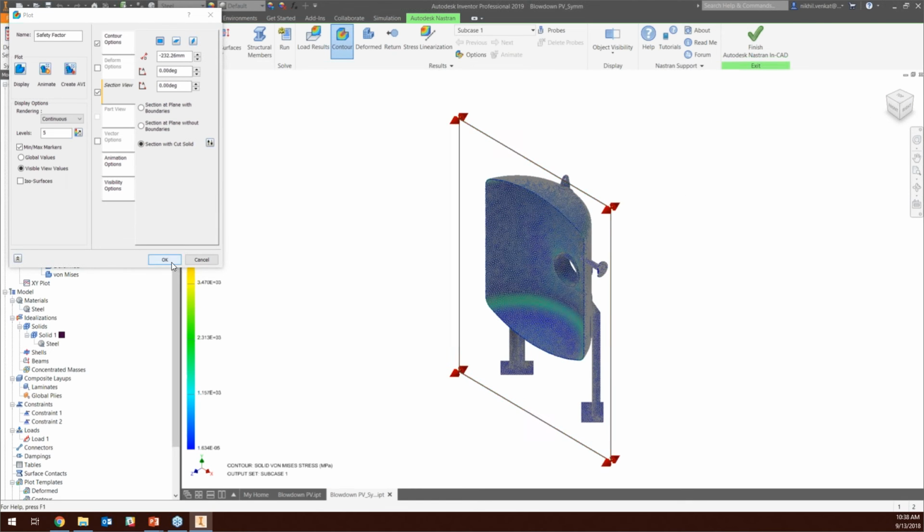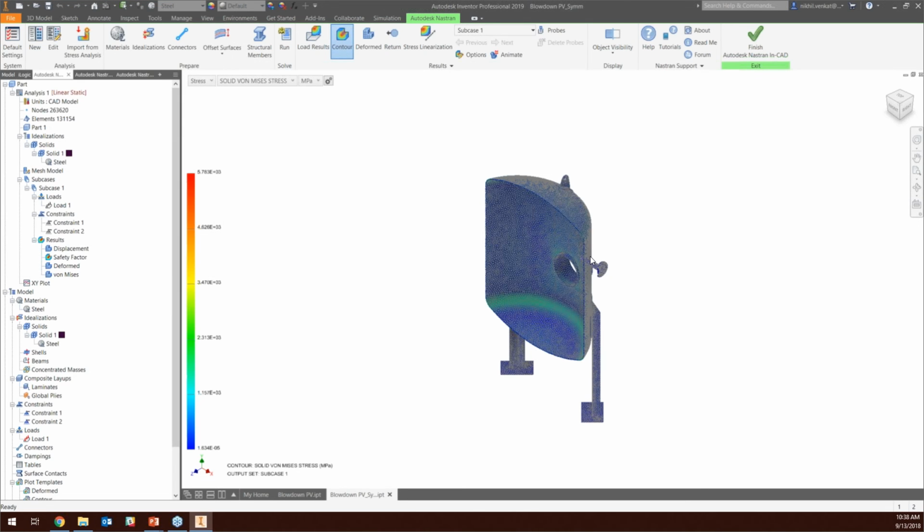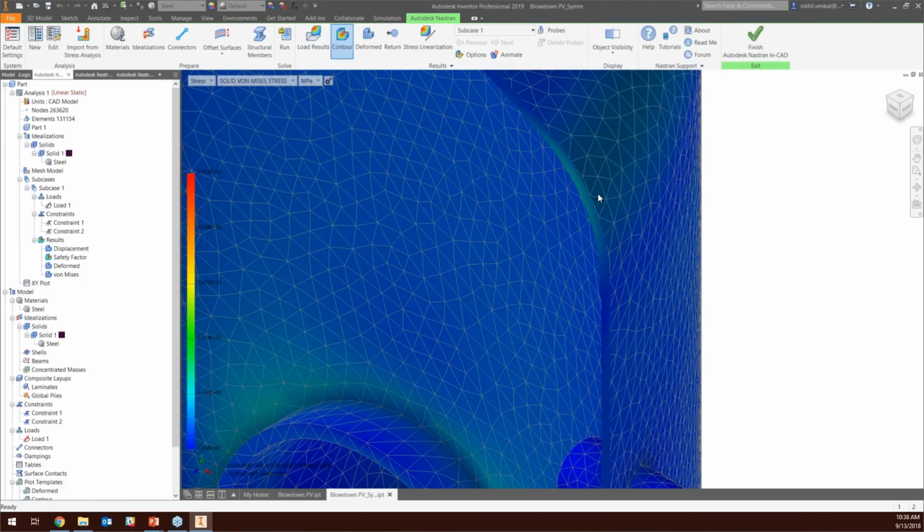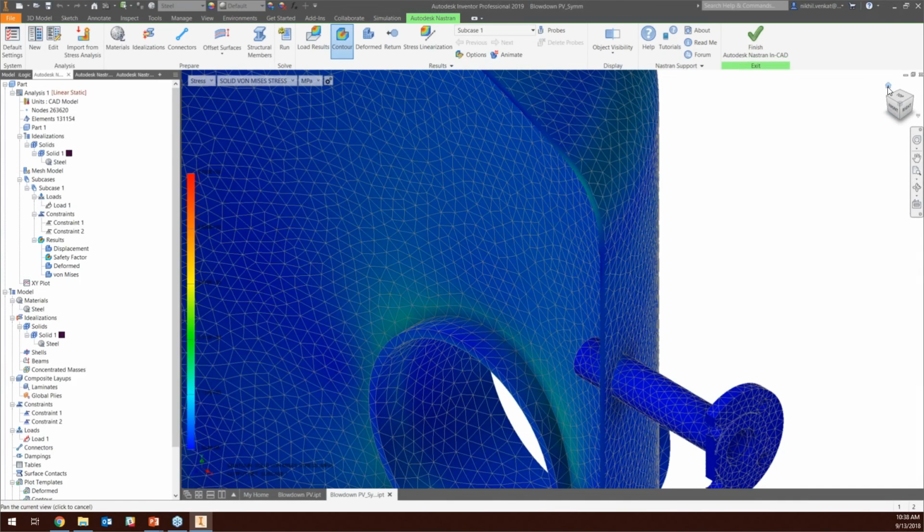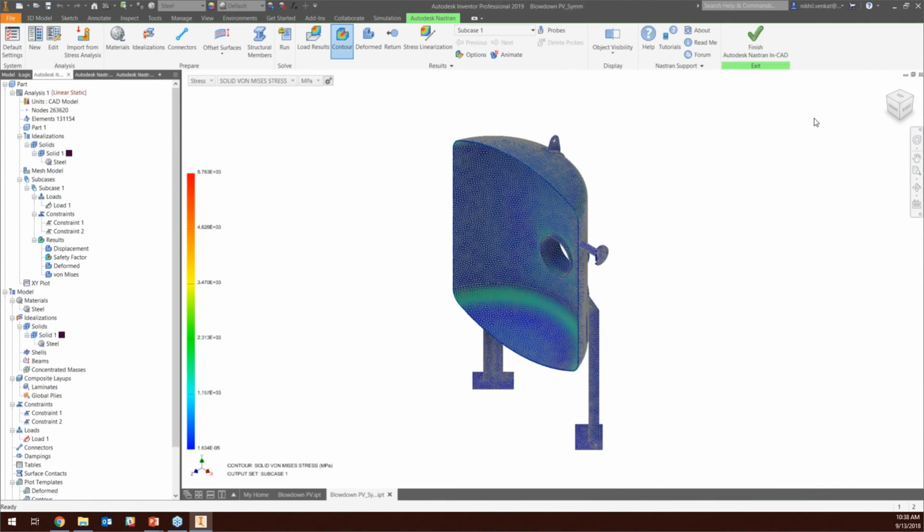And then do it that way. Yeah, and then once you get that section view, you can select something on the inside of the surface and something on the outside of the surface. And then you have information. But it's easier, one, to do the section view, that's the next step. And also, secondly, if you do have a whole model, you're spending more time running it anyway. So it may make sense to just start off with a half section or a quarter section, if that's an option.